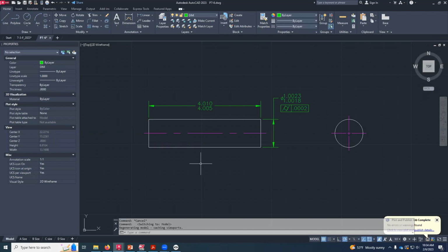And I recommend when you make these parts with tolerances that you just pick one and make it that length. And then you only have to adjust it one way instead of putting 2 adjustments in there. It just makes it easier. Pick one limit and then adjust it the other way down or up. Same way with the diameter. We've got the diameter limits that's given to us there in the drawing.